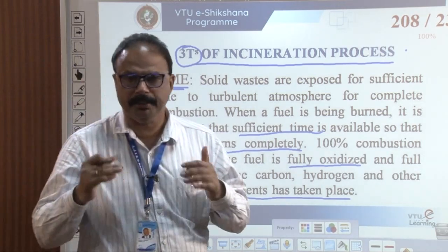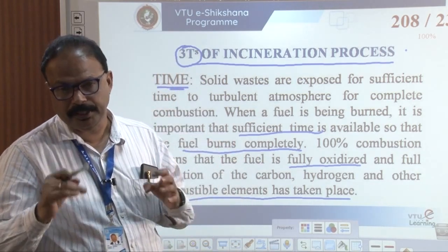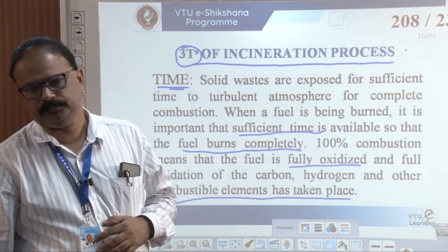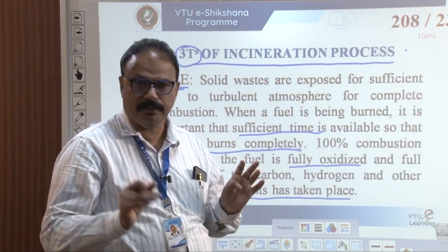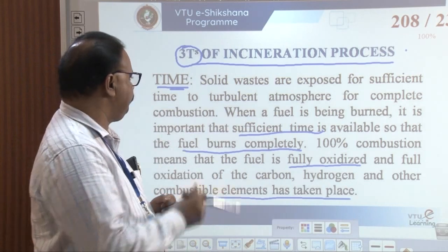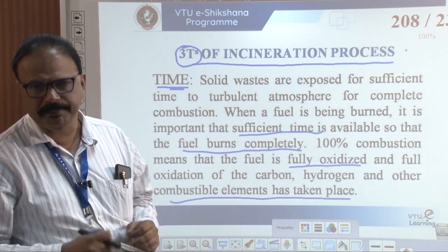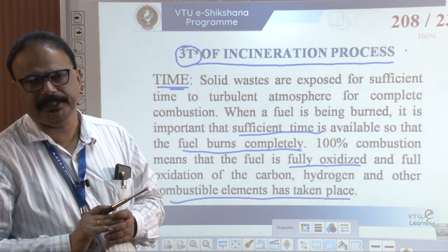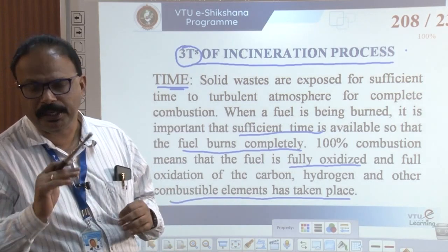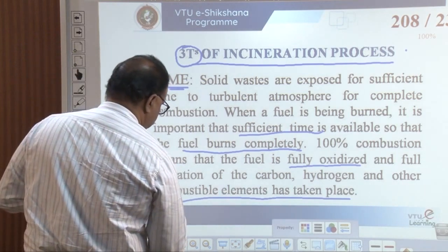This is the importance of the first T, time: exposed to a turbulent atmosphere, when fuel is being burnt, sufficient time must be available for it to burn completely, with full oxidation of carbon, hydrogen and other combustible matter.